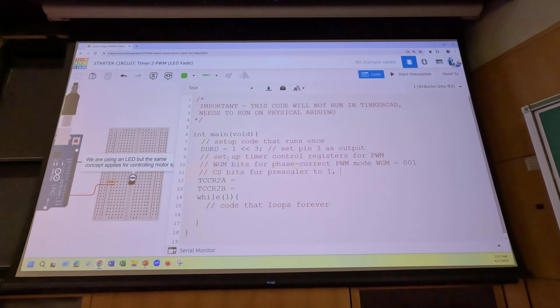but test different prescaler values for your motor. So again, if the frequency of that PWM signal is too high, the motor acts like a low pass filter, it won't actually move. If the prescaler is too big, then your motor's speed might actually oscillate. You'll see it turn on, see it turn off, as opposed to going at a continuous speed. I think when I did this last, I used a prescaler value of 256 and that worked best, but again, all these motors are a little different. The loads on them are going to be a little different. So that is just the initial value to turn it on, but then you're going to want to change the prescaler to see what works best for your motor.